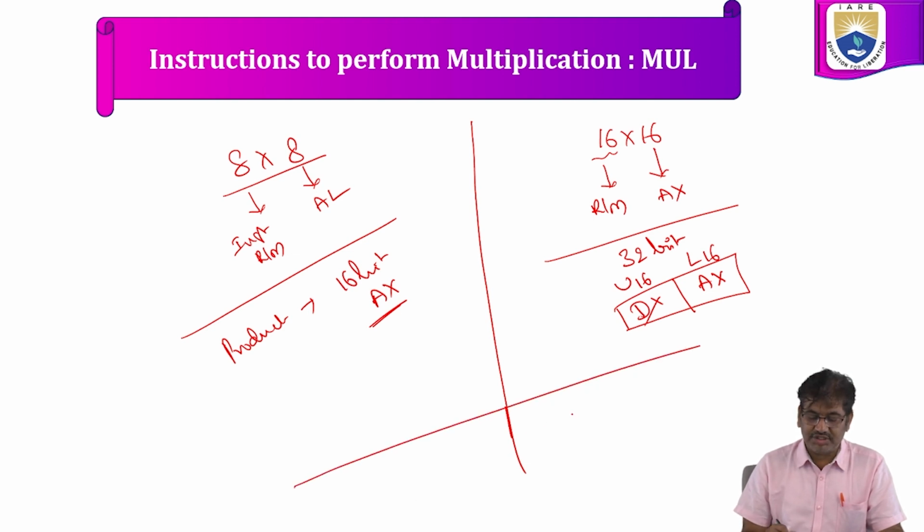The syntax of the instruction: it is only a single operand instruction, MUL OP1, where OP1 can be a register or memory location. Depending upon the size of OP1, it can be either 8-bit by 8-bit multiplication or 16-bit by 16-bit multiplication.